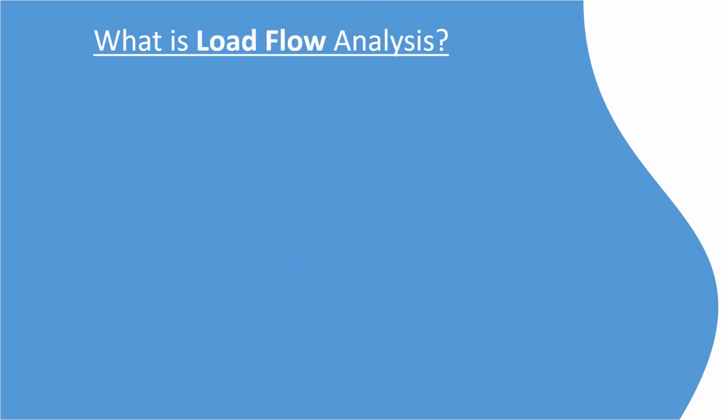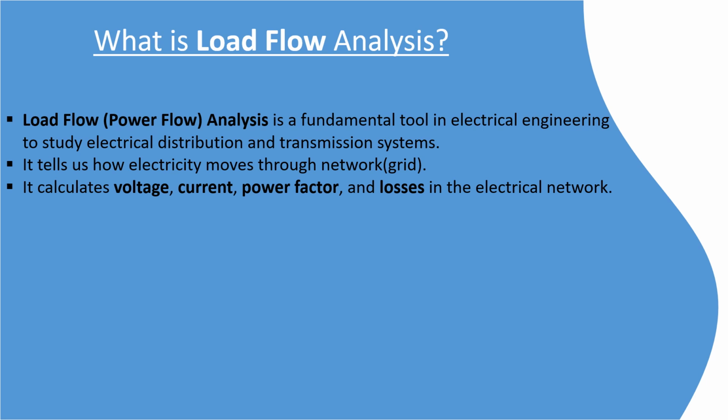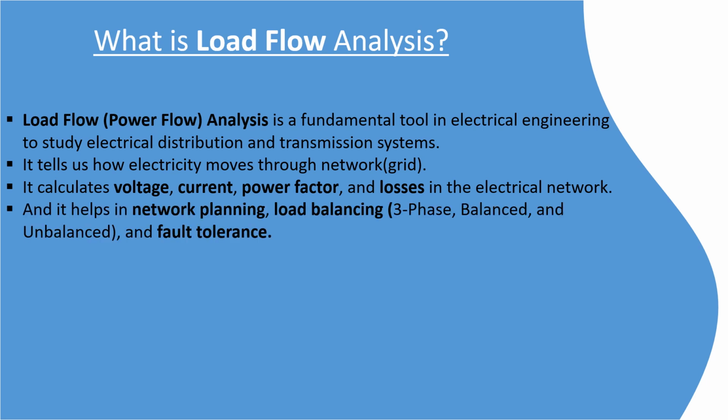First we'll see what load flow analysis is. Load flow, that is, power flow analysis, is a fundamental tool in electrical engineering to study electrical distribution and transmission systems. It tells us how electricity moves through the network grid. It calculates voltage, current, power factor and losses in the electrical network. And it helps in network planning, load balancing like three-phase balanced and unbalanced, and fault tolerance.